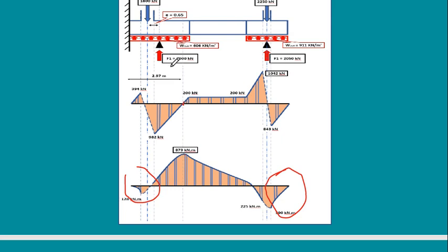How to draw the shearing force? Beam subjected to column from above and soil from below. First, the load of soil acts a little bit alone here, so the load of soil is pushing up. So I'm going to go like this. Once I reach the edge of the column, the load of the column takes the shearing force diagram below till the other edge of the column. Once I reach the other edge of the column, my soil starts to push again till I reach this location. Once my footing ends, I don't have any loading.